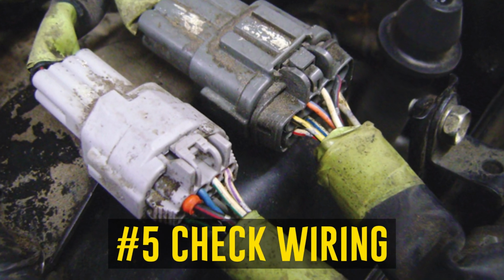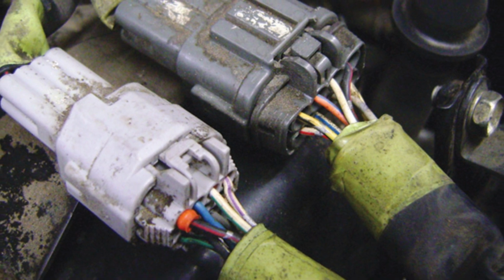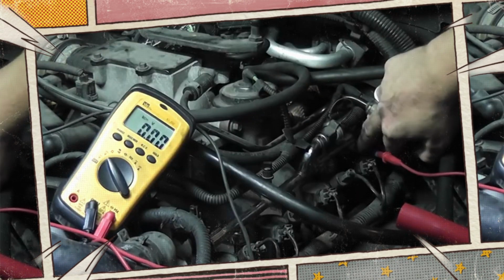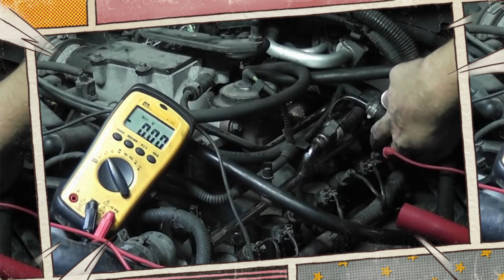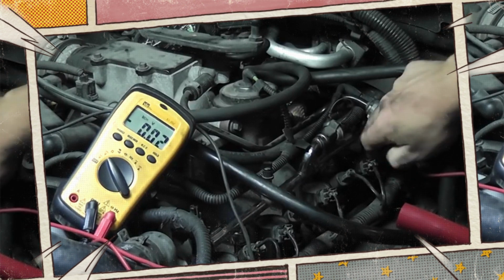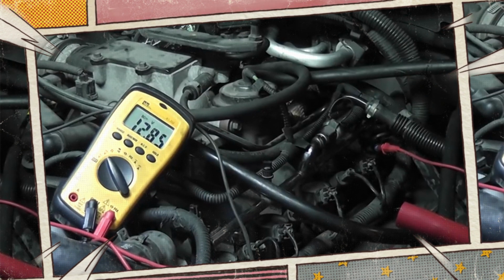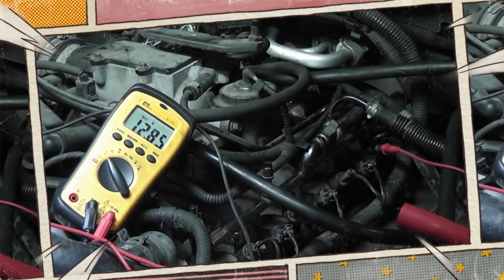Check wiring. It is recommended to verify the continuity of each wire in the number 3 injector harness if the P0203 fault in your car continues. A factory-specific wiring diagram and a digital multimeter can be used for this. From the connector ends at the injector to the terminating ends at the ECM or PCM, every wire should be continuous. If not, there is an open circuit and more testing needs to be done.